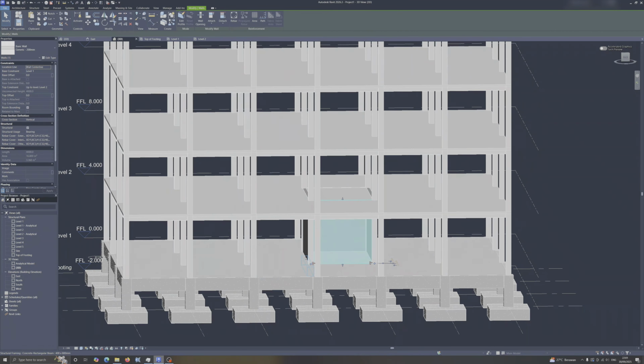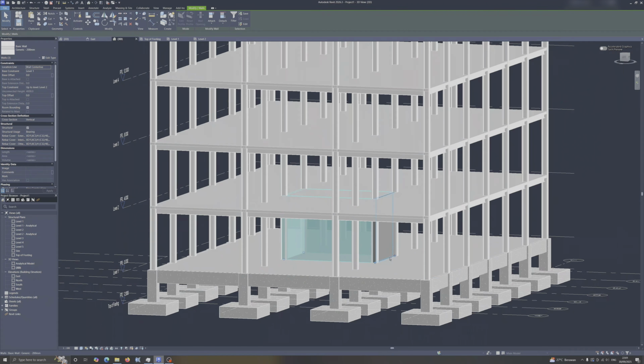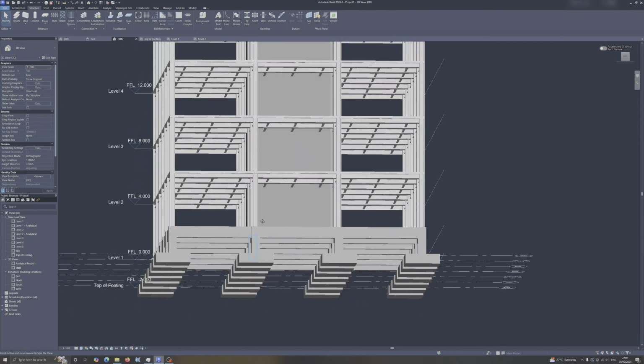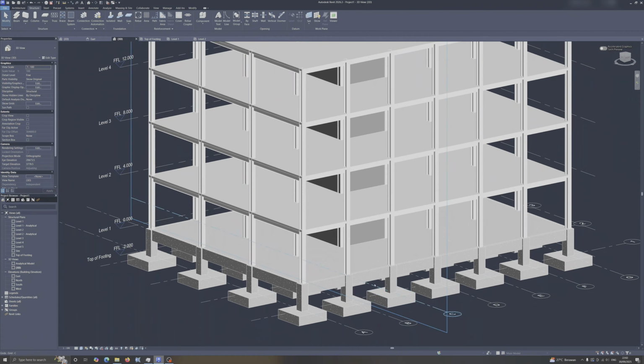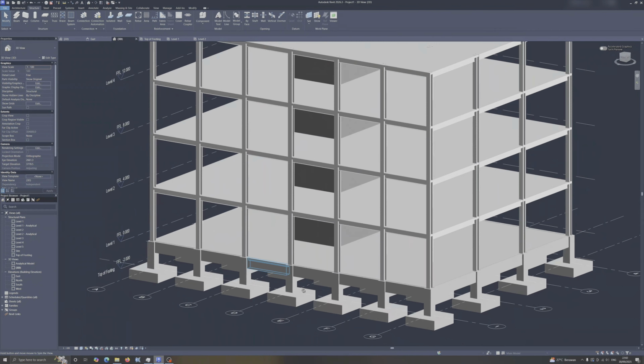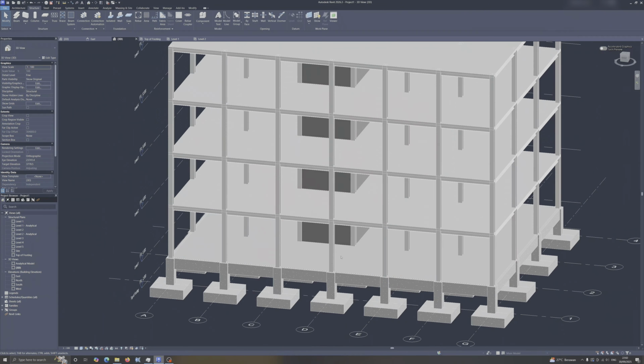And you can select the shear wall like so in the 3D view. And you can copy to the clipboard and paste it to 3, 4, and 5. Like so. One thing I forgot to do in the example was to model in the foundation requirements for the shear wall. So I guess we can overlook that for now.